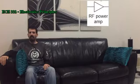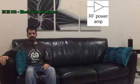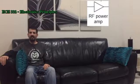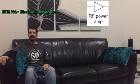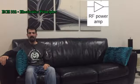So a power amplifier is needed to prepare the signal for the antenna. To reduce cost and size of the circuit, the power amplifier can actually be designed into the mixer, allowing one CMOS amplifier to function as both the mixer and the power amplifier of this radio circuit.